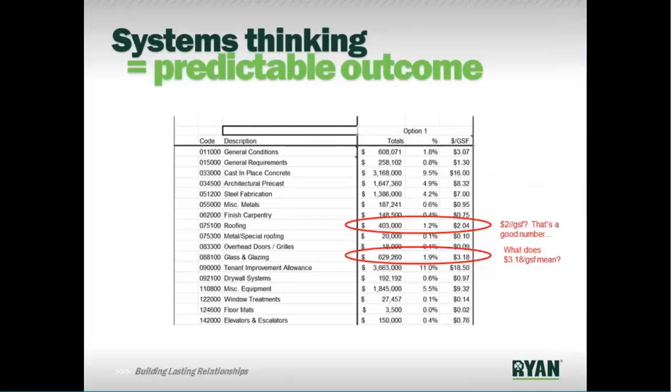Along those lines, it's worth pointing out that part of the move in the cost model stage is to look at things from a systems basis, using Uniformat, which is the industry standard, rather than the CSI and MasterFormat. And this is really the backbone of why our template is set up like it is, and why we're trying to capture cost information the way that we are.